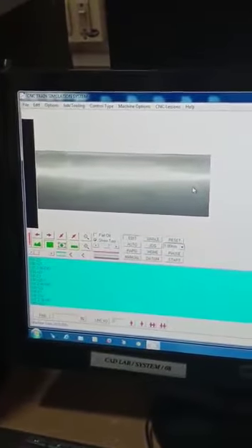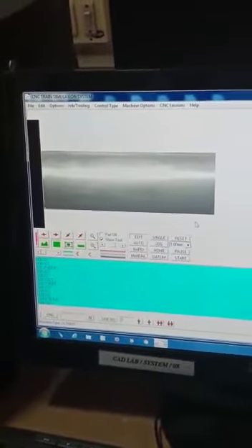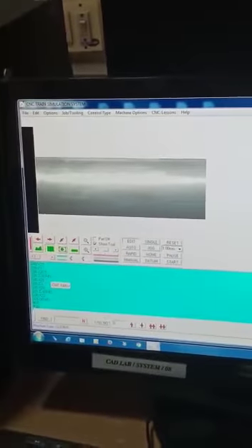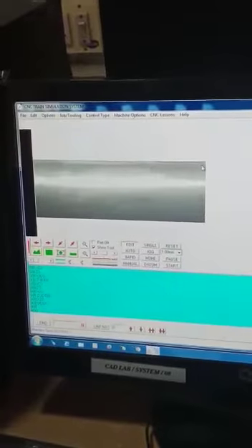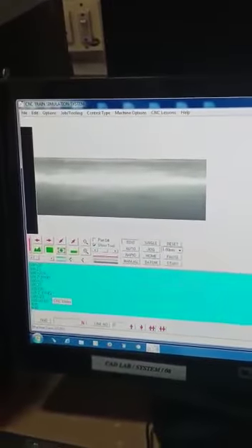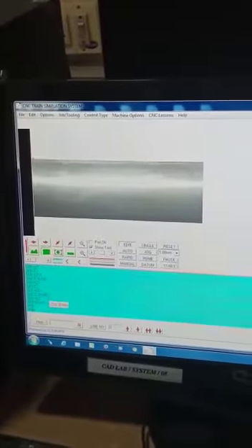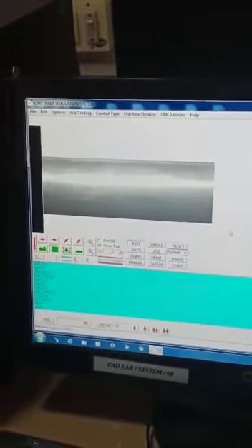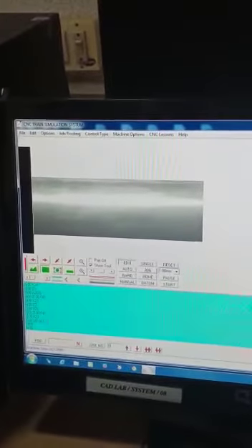So already 1.5 has been faced from the 22. Now it must face here at 20.5, meaning 0.5 must be reduced. So again G01 Z minus 30 F45, G00 X23 and Z3, so it comes to the reference point again. Now according to the dimensions it must be finished to 28. It must go 2 mm apart from your part, so in Z 2 mm and X 1 mm. So again, G28 U0 W0, come to your reference point, and M05 spindle stop, M30 program end.